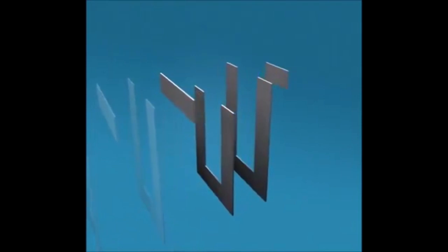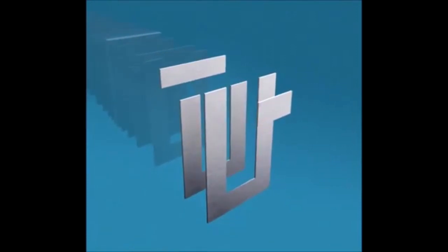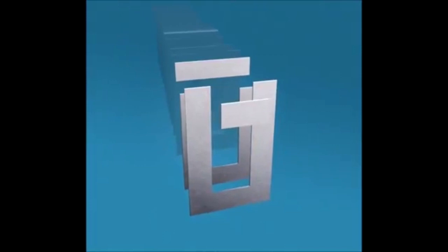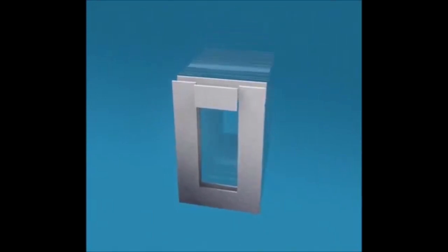This circulating current is produced mainly due to the EMF induced in the iron core, as it is constantly being subjected to the changing magnetic field set up by the external sinusoidal supply voltage Vin. To reduce these unwanted power losses, thin steel laminations are used to construct the transformer core.